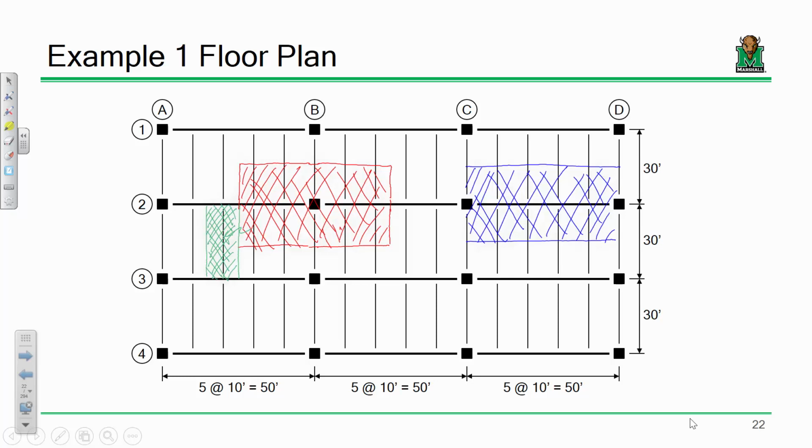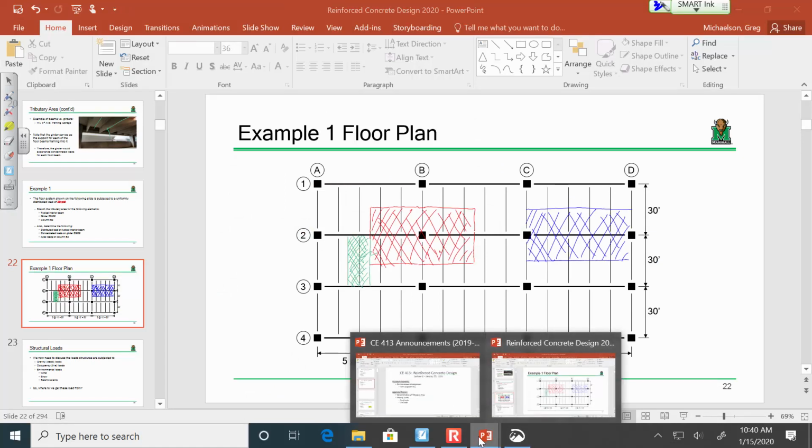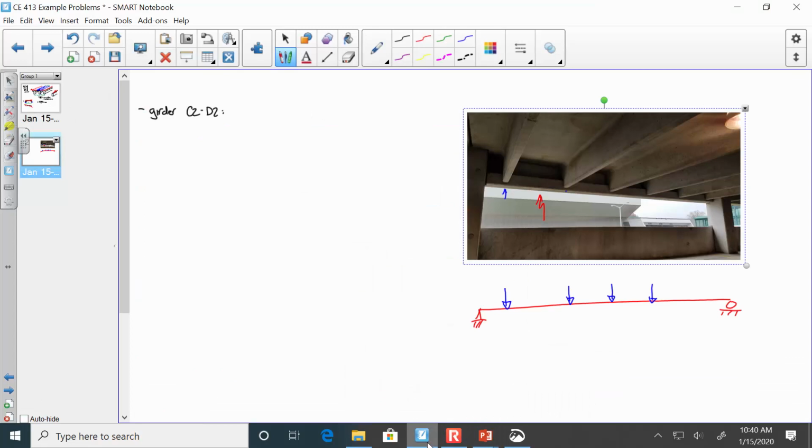So here's what I propose. Now, how many frame in here? Here's the girder. How long is the girder? 50 feet. And so I've got framing in at every 10 feet? So I've got a girder that's 50 foot long, and I'm going to have a point load every 10 feet. And those point loads are going to be from the beams. So I want to ask you, so far, based on what we've said, would you agree that the model for this girder is going to look like this? Got a girder, this dimension, 50 foot long, and every 10 feet, I'm going to have a point load. That'd be a fair statement?